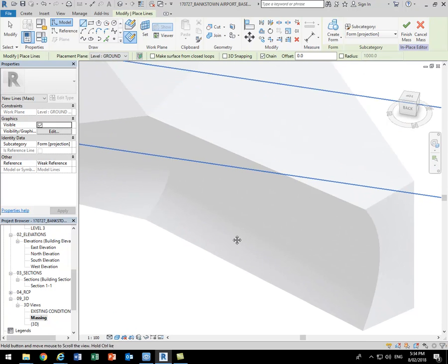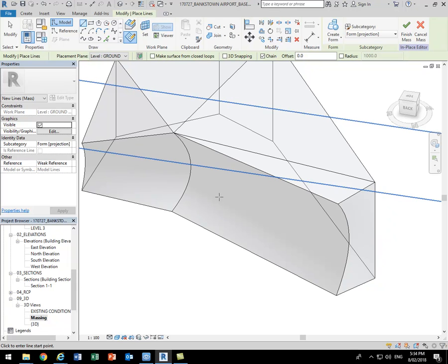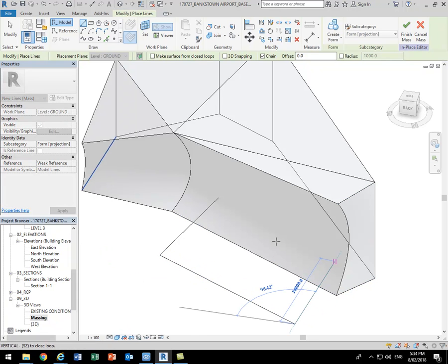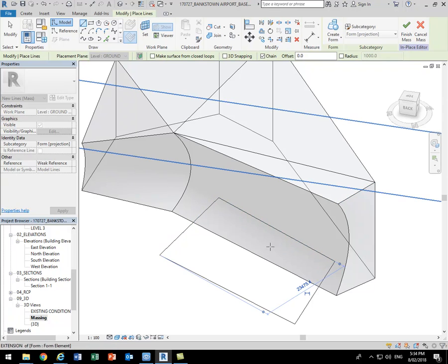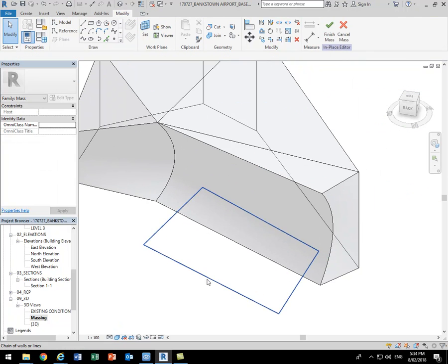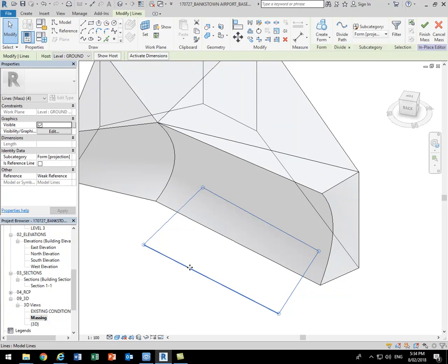and then do a shape that's going to be a void, so I'm just roughly drawing a sort of rectangular shape that would be in plan. Doesn't matter, I can adjust that. Okay, so I've got my shape, now I'm going to select it, and then on the sub-menu under Create Form, I'm going to choose Void Form this one.